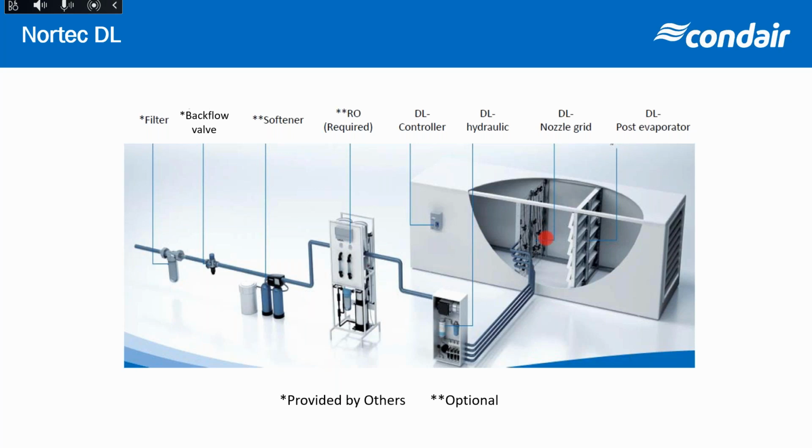Instead of all that water going to drain because we're asking to do a lot in that section, that's the whole purpose of adiabatic technology. We are converting that liquid to a gas using the energy in the air as opposed to a utility. And 2 feet is not enough time for that water to be absorbed. So under normal circumstances with different equipment, a lot of that water would go to drain. But in this case, with the hybrid technology, the water doesn't saturate, it actually sits in these thousands of pockets of holes in the ceramic media, and then it becomes evaporative.